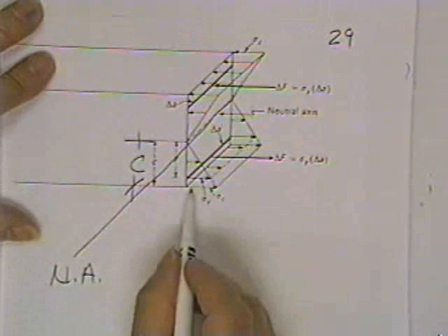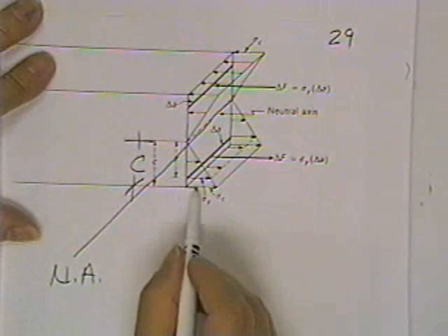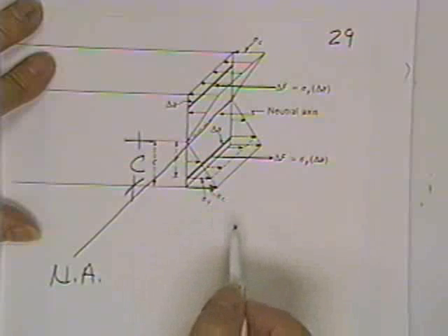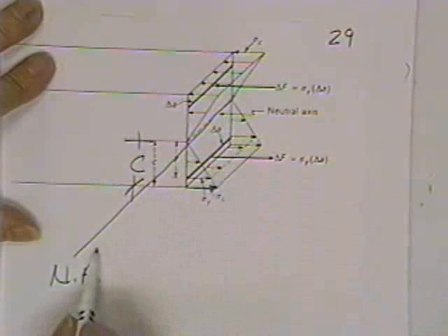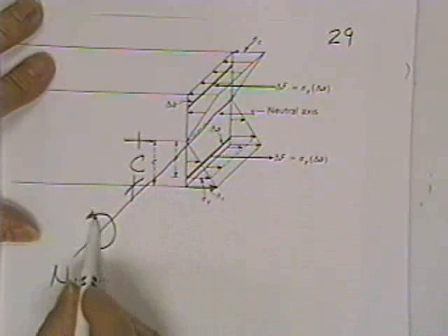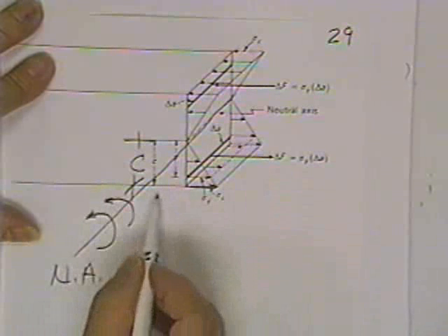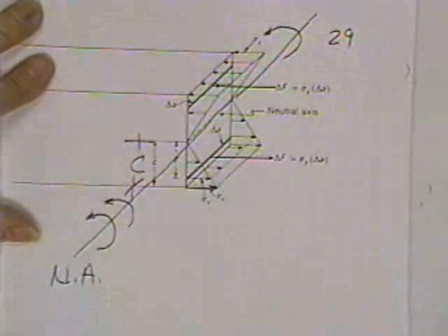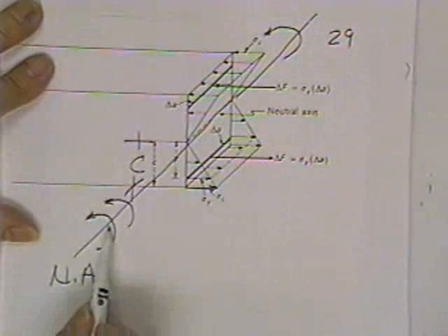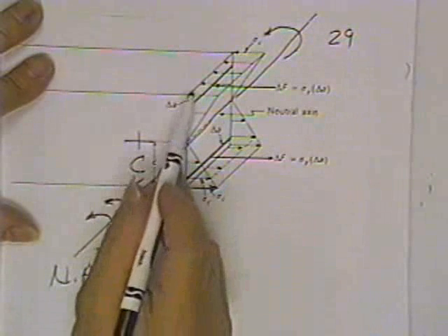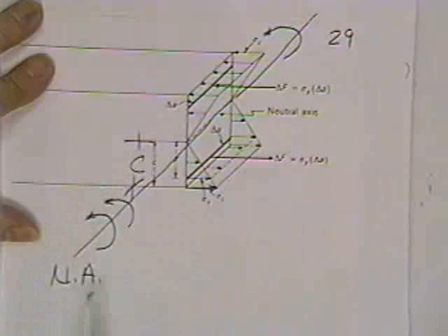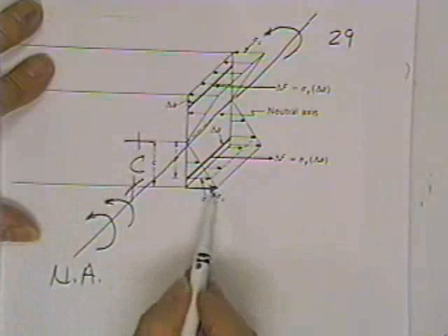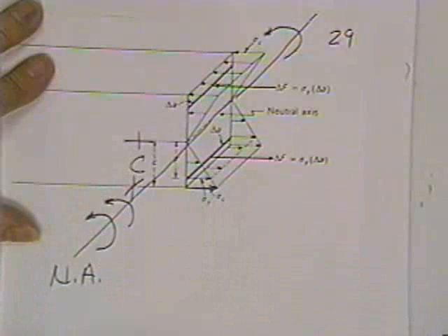Here are your stresses on the outside fiber. You'll notice that they are biggest on the outside fiber. This particular beam is being bent like that, and the reason I know is because these little arrows are banging into this surface, causing compression arrows on the top, causing stretching or tensile stresses on the bottom.